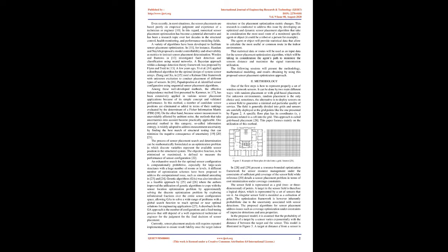According to 9, a global path planning consists of a path planning algorithm applied over the entire target environment, a map, a floor, a room, corridor, building, etc., that, in general, demands more computational resources to calculate different alternatives and routes to be used by the mobile platform and managed by a central control system. A local path planning is the embedded algorithm used frequently and dynamically by a robot to avoid immediate obstacles that were not considered by the global path planning, but they are present in the same pathway designed by the global path planning. A key element to improve accuracy of positioning systems is how to cost-effectively place sensors to collect meaningful response data, so that the data well characterize fundamental navigational properties.